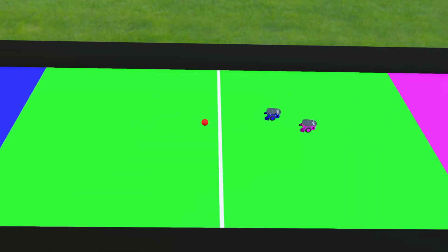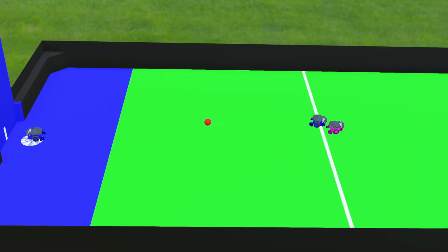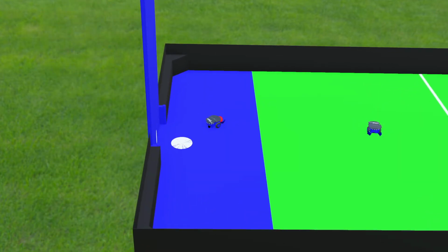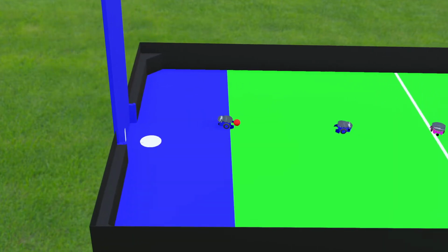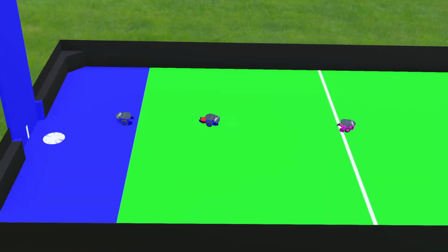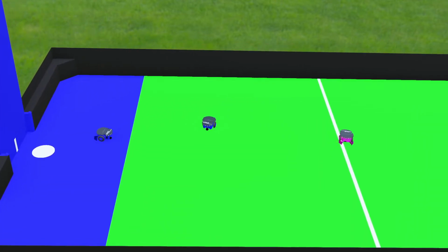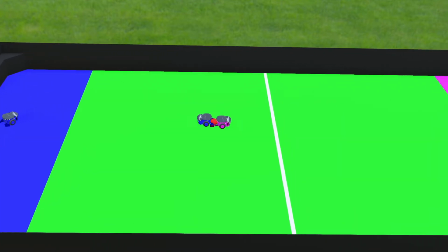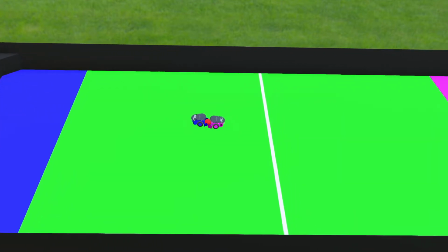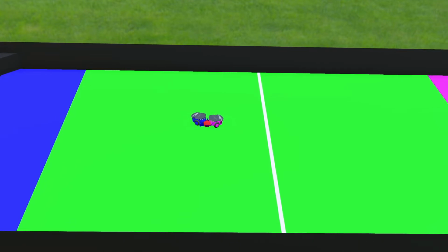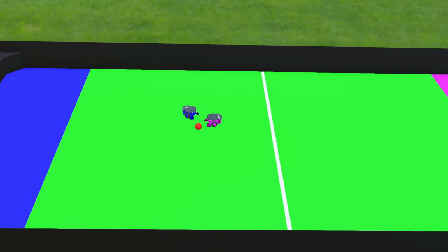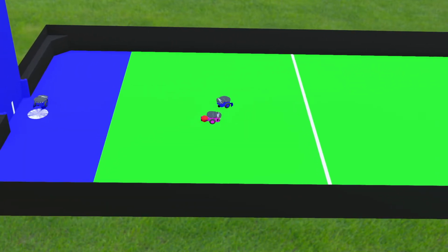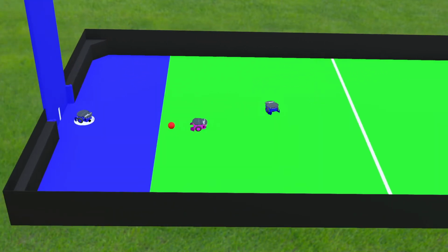The way it aligns itself is there's a camera that points slightly up, which detects a certain color. If you notice the blue goal there is going right up to the sky, that's so the purple robot can detect that blue color with the camera that's pointing up. So the aim state will turn the robot until that camera spots the color that it's after, and then it will stop turning and go to the next state, which will open up the grabbers.